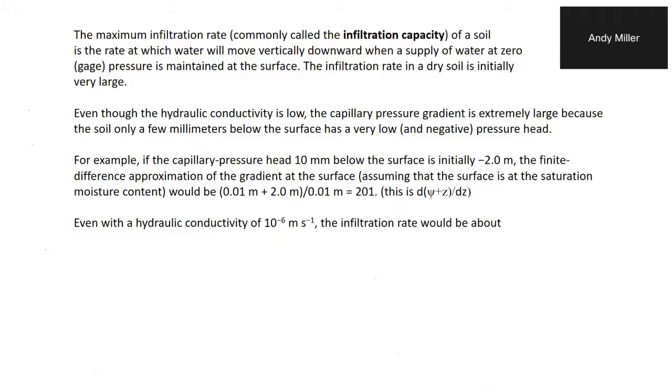Darcy's law, right? So what does Darcy's law tell you to do to figure out how fast that water is moving? Hydraulic gradient times K. Okay, so let's calculate it.